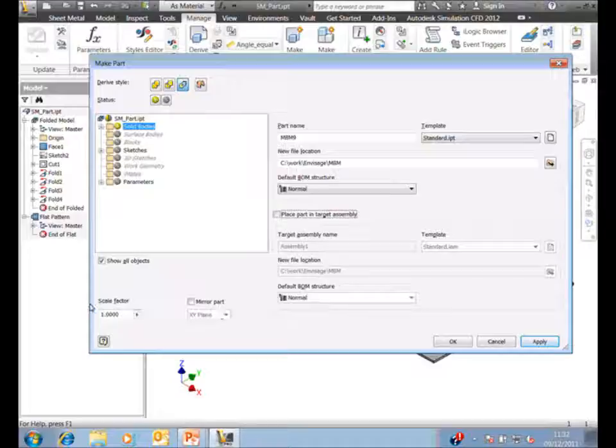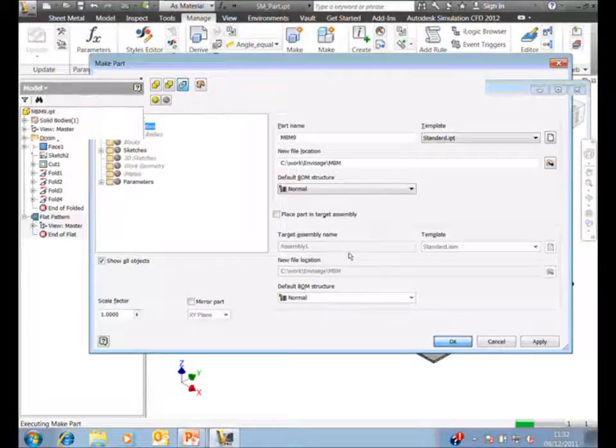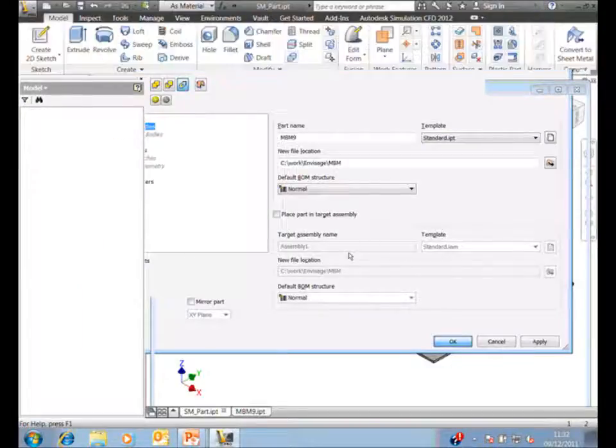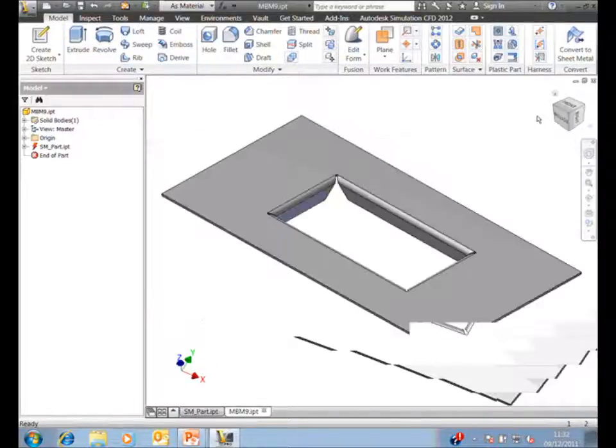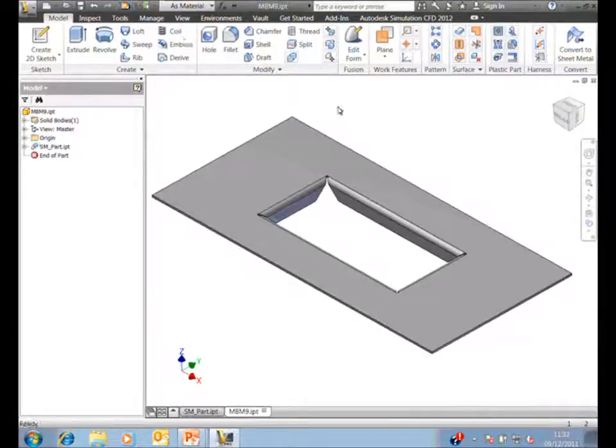Information here is quite useful if you're working with plastic parts. If I need to take a plastic part and send it across to a derived component and take into account shrinkage, I can add a scale factor in this box here as well. Okay, so let's create our derived component. And there's our sheet metal part. Just update it from the original part file.